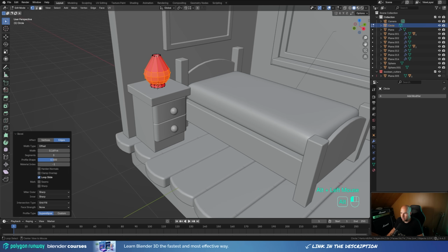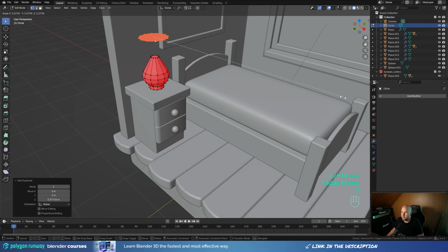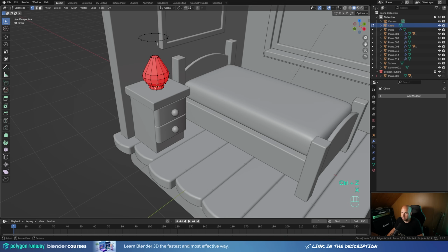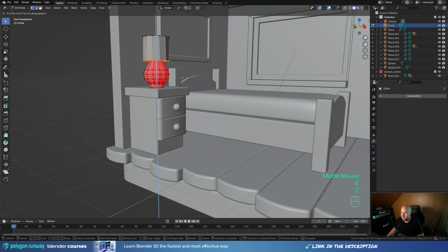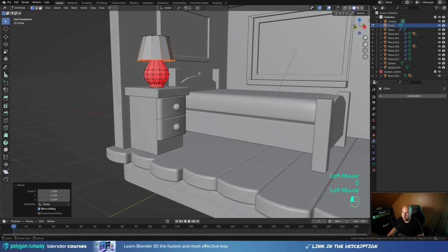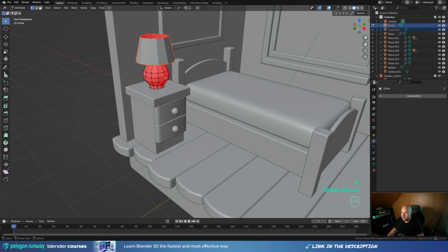And additionally we can alt click the top loop, press shift D, then Z, and move it up. Press S to scale, press X and delete only faces, so we're left with this. And press E then Z and extrude this down, and press S to scale it up a little bit like this. And finally we can add some thickness to it, but we can separate it. So press L, hovering over this, press P and enter to separate the selection. And of course let's press A and shift N to recalculate the normals for the bottom one.